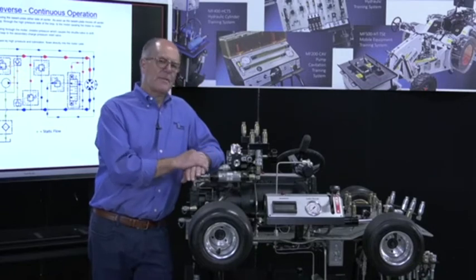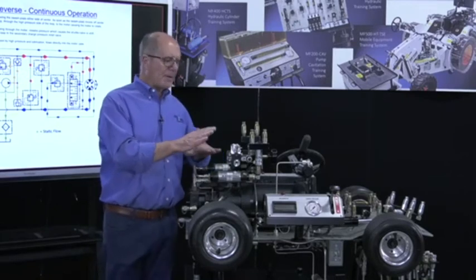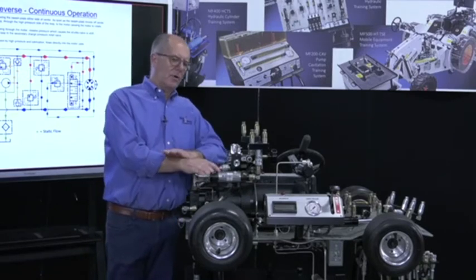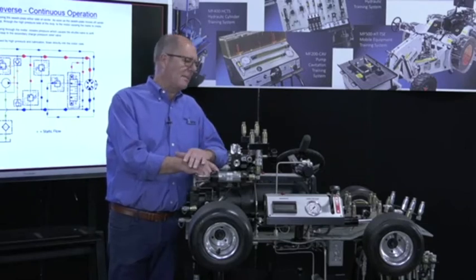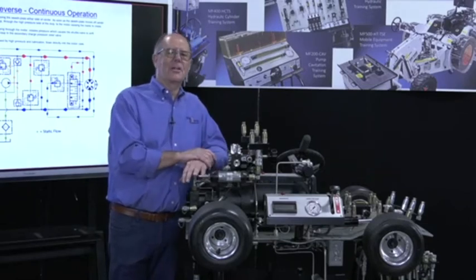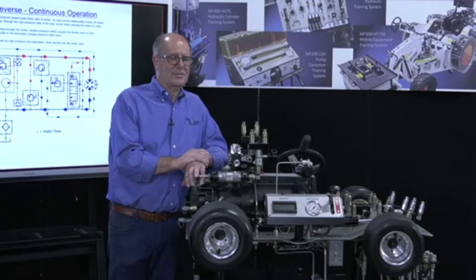So if I have a catastrophic failure on a pump or a motor, the smart way forward is to replace pump, motor, and all high-pressure lines, flexible. I mean, you're talking about a $50,000 transmission and maybe $350 worth of hoses. It just doesn't make sense to leave the old hoses in.